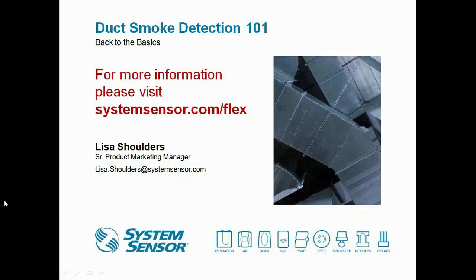When you install a duct smoke detector, there could be condensation or any sort of water inside the duct. That water, if it got into that sampling or exhaust tube, would just run straight into your detector. So that would just be something to do as an absolute last resort. But if you can install it in any other orientation, I would do that prior to installing it on the bottom.